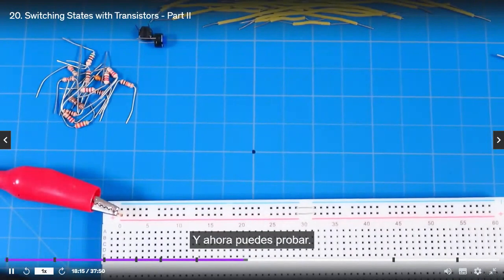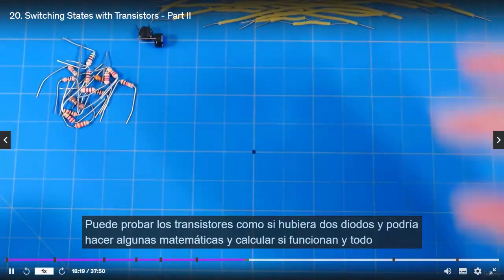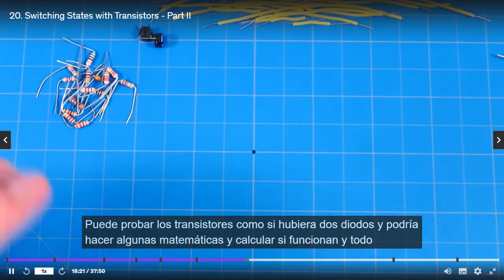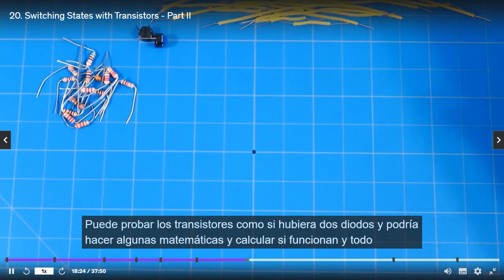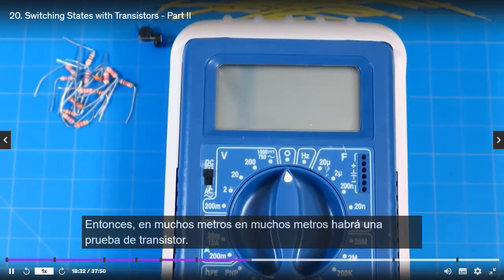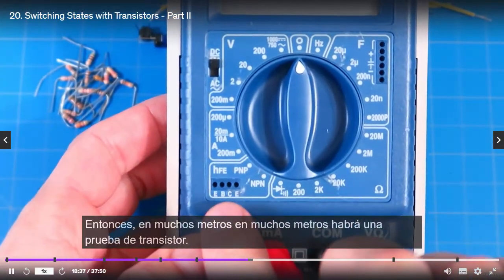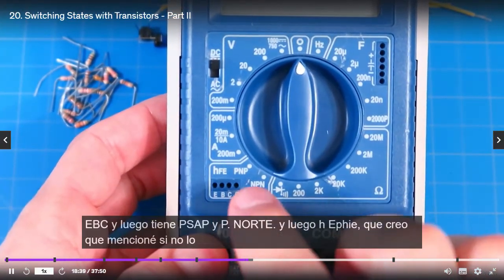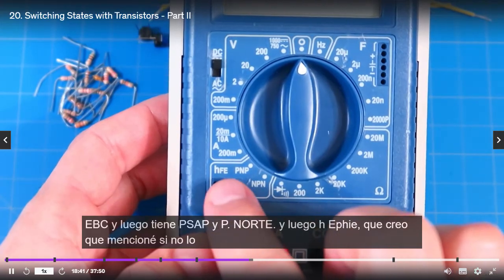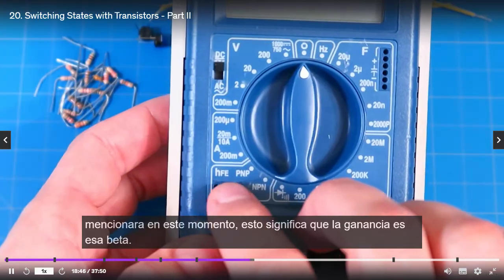Now you can test transistors as if they were two diodes, and you could do some math and compute if they work, but rather than do all that, let's just use a tester. I actually have a transistor tester. In many meters there will be a transistor test. See this right here, EBC, and then it's got PNP and NPN, and then h sub FE, which I think I mentioned. If I didn't, I'm going to mention it right now. This means the gain. This is that beta.